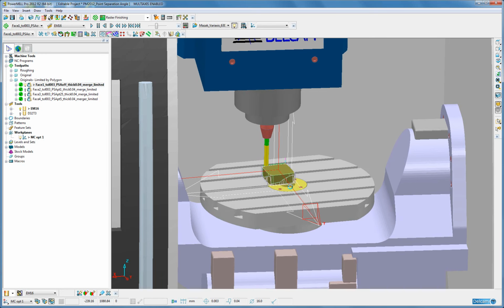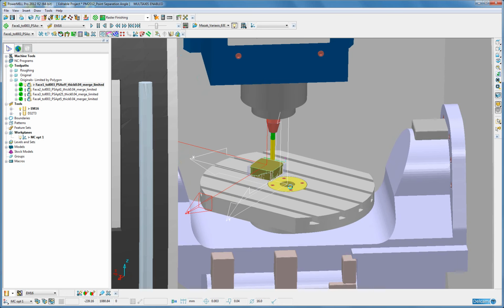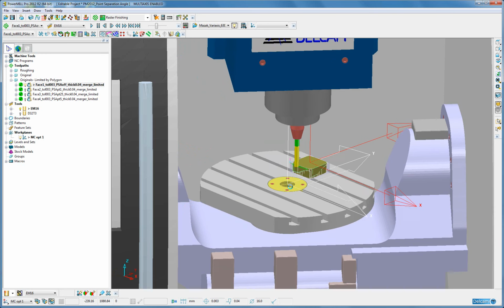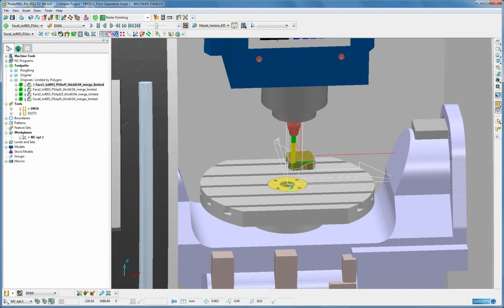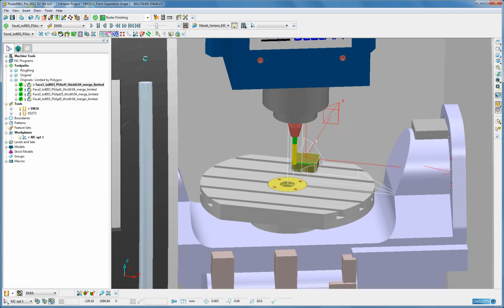What happens when we look at the component that has been machined is that when we have a rapid change like this over a small area, marking on the job can typically be seen. This angular point separation control works to complement the existing point separation distance.